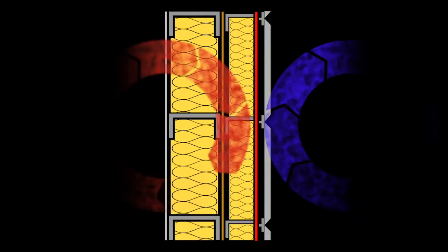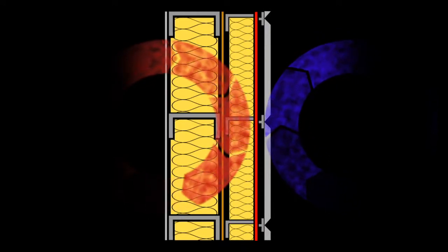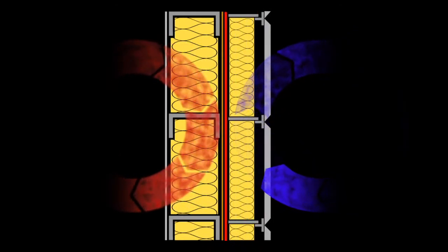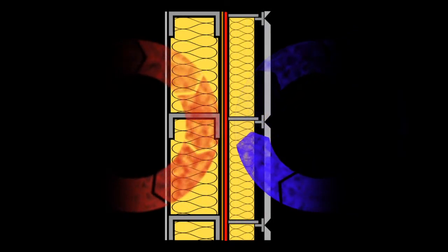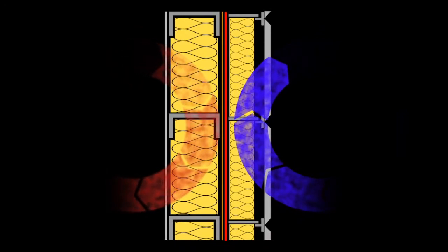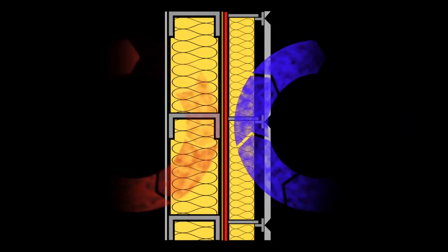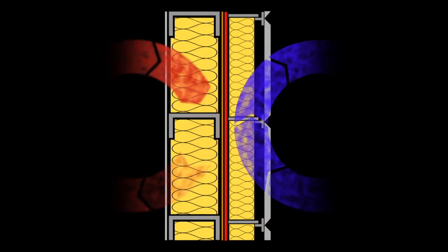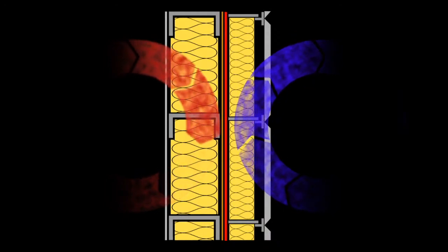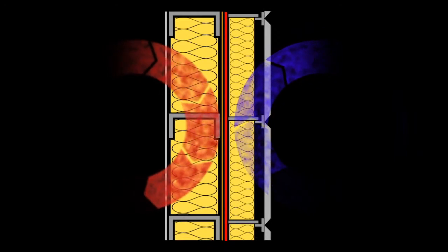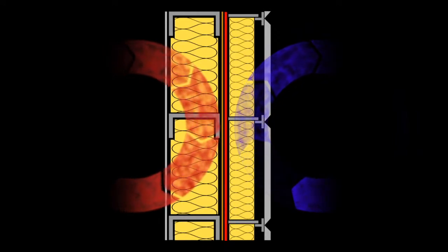External systems require good vapour permeability to ensure moisture is not trapped within the construction, and this opens up a third possibility. This is to position the air barrier layer within the construction, over the structural sheathing board, but behind the outer layers of the thermal insulation. This increases the protection to the air barrier layers and can help simplify detailing of the membrane. Care must be taken with this method to ensure wind washing through the outer insulation does not occur, for example with use of a vapour permeable jointing tape on the insulation boards.